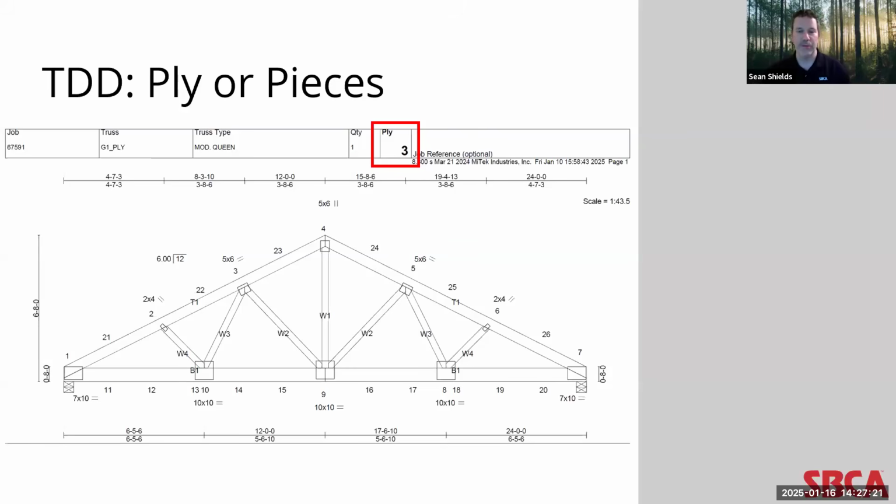One possible reason for this regional difference is weight. A pre-assembled multiply girder weighs a lot, and typically a crane or at least a piece of heavy equipment will be needed on the job site to hoist a multiply truss into place. Cranes are more commonly used in places like the Midwest than in the South. But that isn't a hard and fast rule.